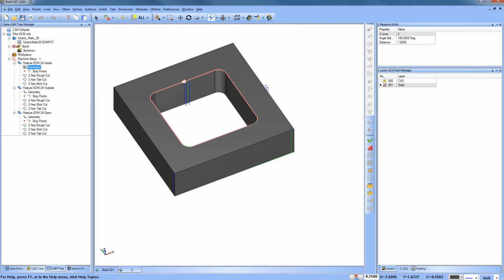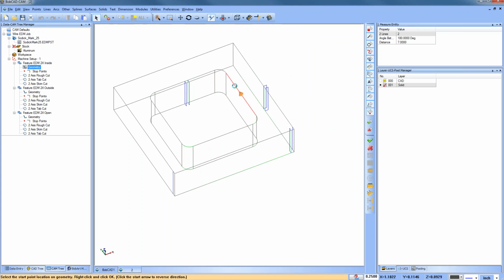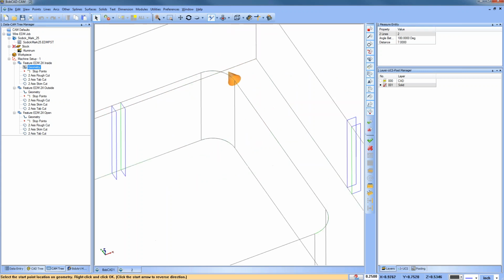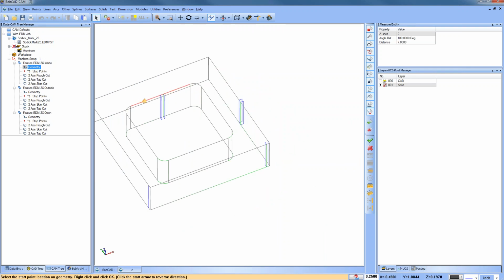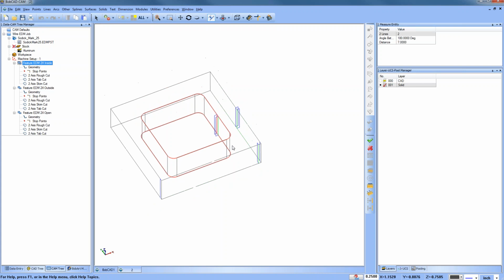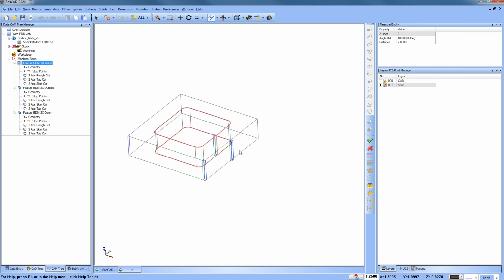The other thing you're looking at here is if we want to move it, we can right-click, modify start point, and we can click on any of the snaps. What it does is actually pick up all the snaps. So it's either middle, end, 0, 45, 90. These are the standard snap points. So you can get an idea of different places that you can put this. So we can move that to a different location. You use the space bar to lock it in, recompute to update the toolpath. So that one moved it over to here.